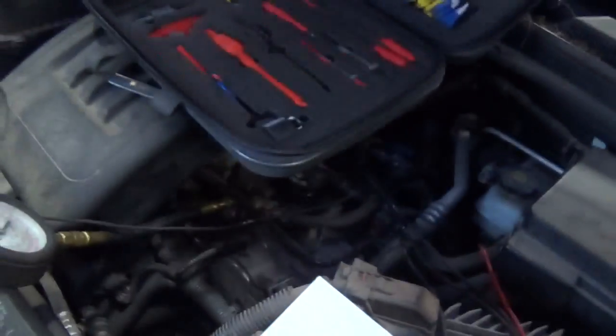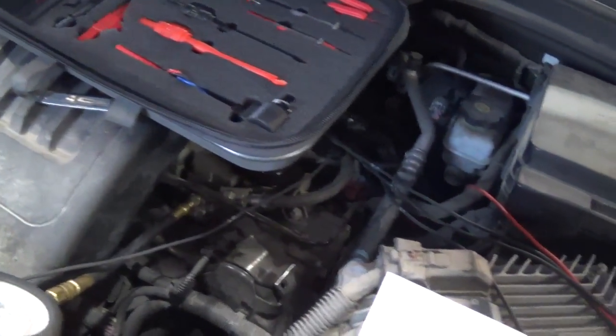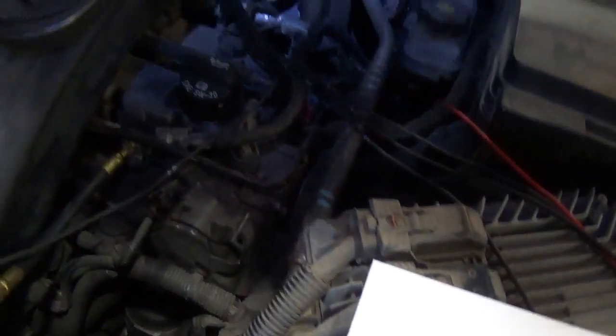The question is, is the solenoid mechanically moving, opening and closing an oil passage? That's still one variable. But the way this thing cranks, it does not sound like a normal cranking sound. It's kind of like, so I'm thinking we're heading towards a timing problem here.